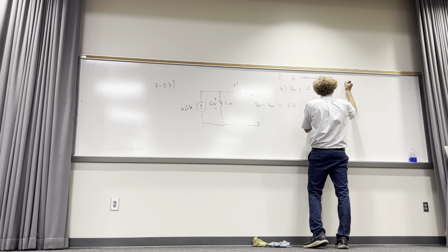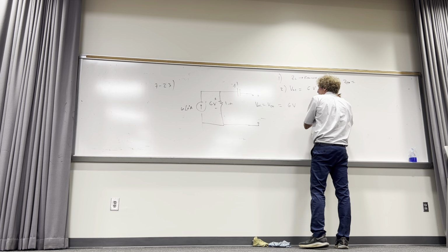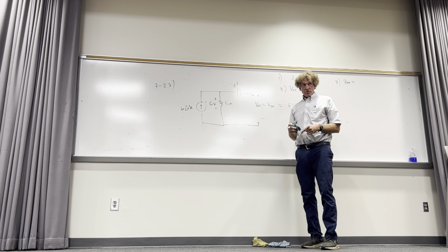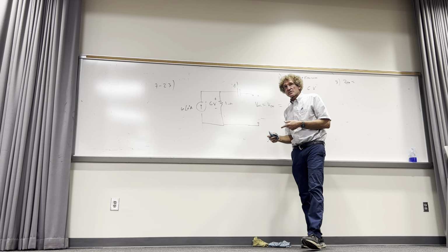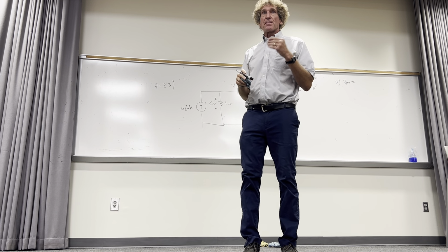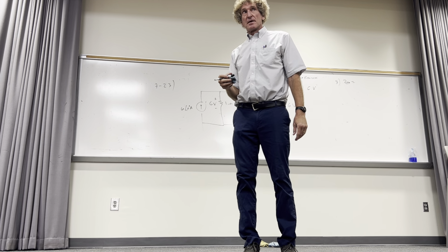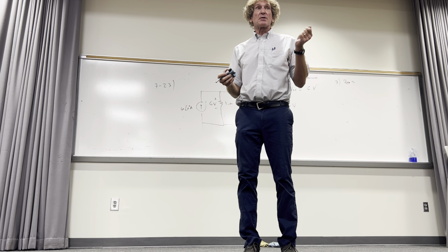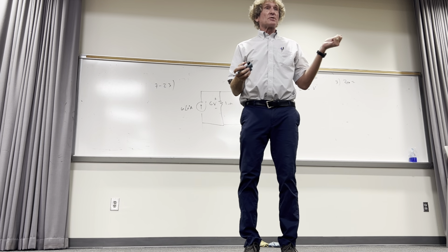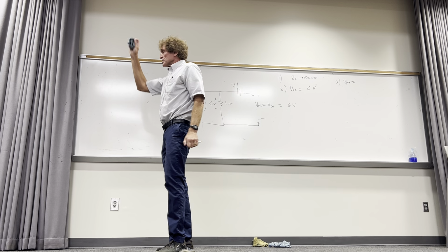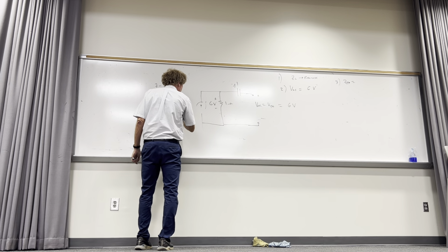Finally, the third thing is I need Z Thevenin, or the Thevenin equivalent impedance looking back, right? You agree with this? What do we do with a current source? There's a live current source there. What do we do with a current source if we want the Thevenin equivalent? Well, we turn them off. When you turn a current source off, the current goes to 0, or it becomes an open circuit. Do you all follow me, class, on that one? So you might as well just erase it.